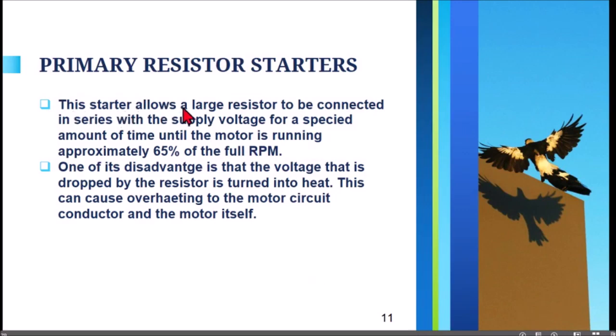This starter allows a large resistor to be connected in series with the supply voltage for a specified amount of time until the motor is running at approximately 65% of the full RPM, the revolutions per minute. So when the motor is starting, the primary resistors connected in series will engage.